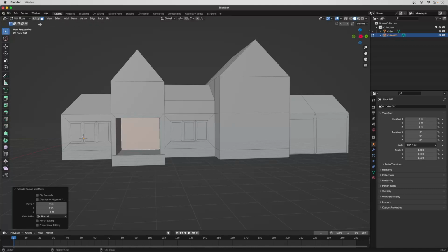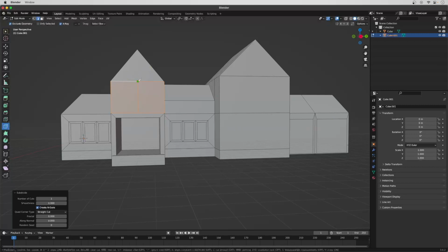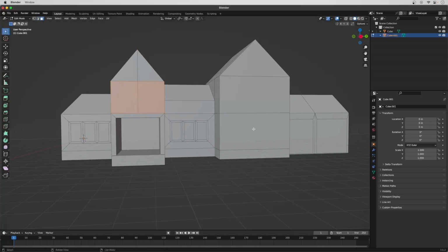Now I'm gonna go to my knife tool. Now I'm gonna subdivide these 2 edges. Subdivide. Now I'll go to knife. Select this one. And on the Z axis, so click Z. There. Now you need to click your space bar to get rid of the knife still going. Now I'll go to face and this one. I'm gonna go to Edge Select. Select these edges. Subdivide them. Now I'm just gonna keep 2. Actually, I'm gonna do 1.